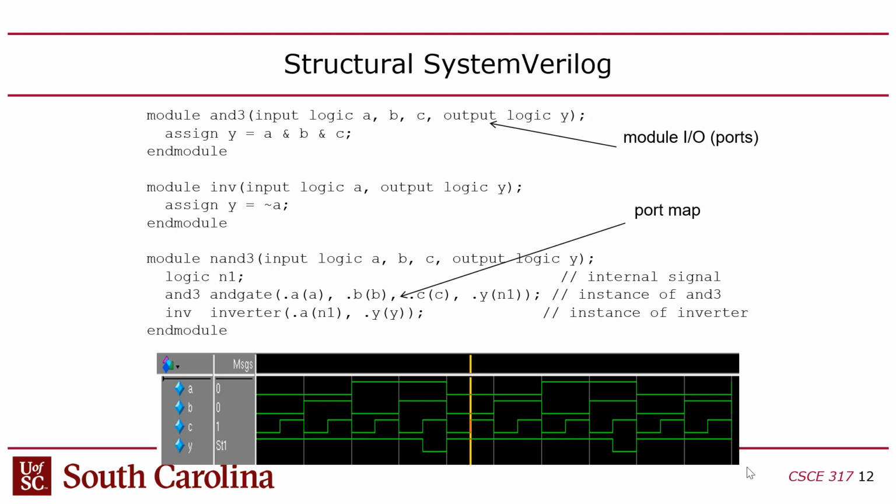In Signal Tap, you don't have to worry about this. All you do is you go into the Signal Tap tool and you just create a table of signals you want to monitor in the FPGA in your Verilog design, right? That's all you got to do. And then the tool will put in a memory that allows you to store samples of those signals in a table, 1 per cycle. So you have to give it a clock, and you have to give it a memory size, which, the default is 256, but you can bring it up to like 8K if you want to, or 16K.